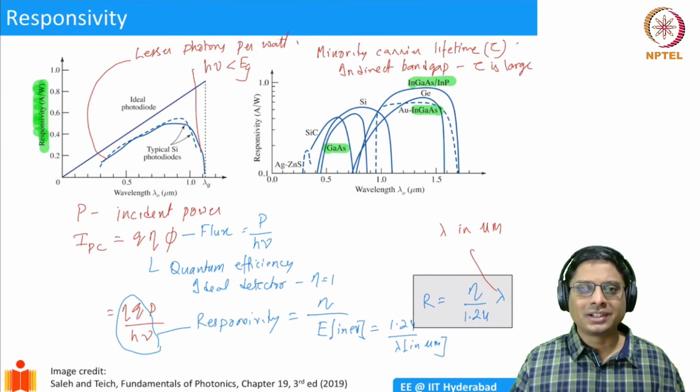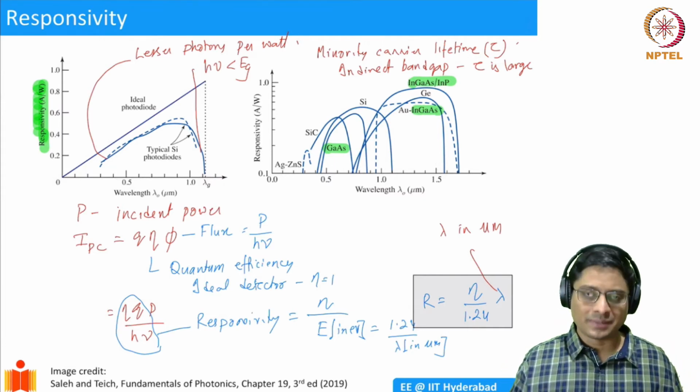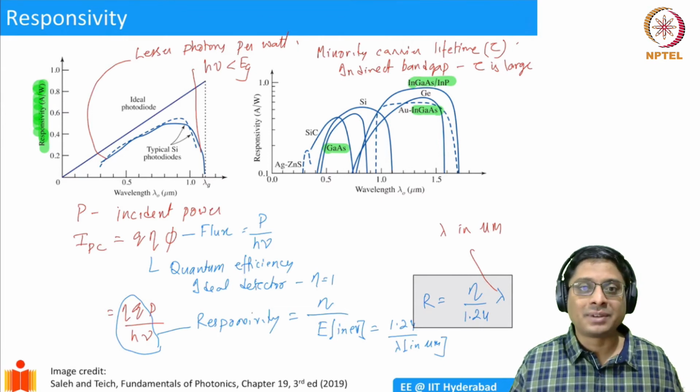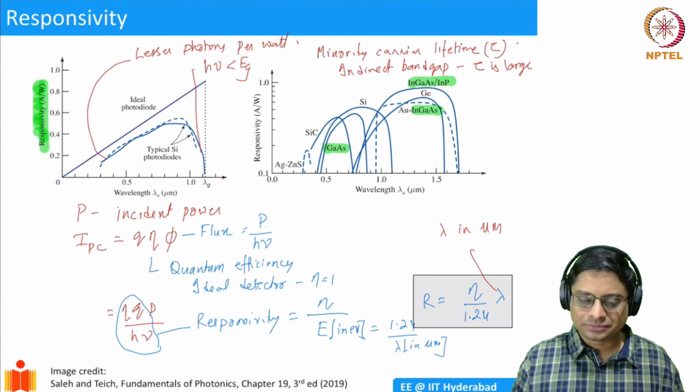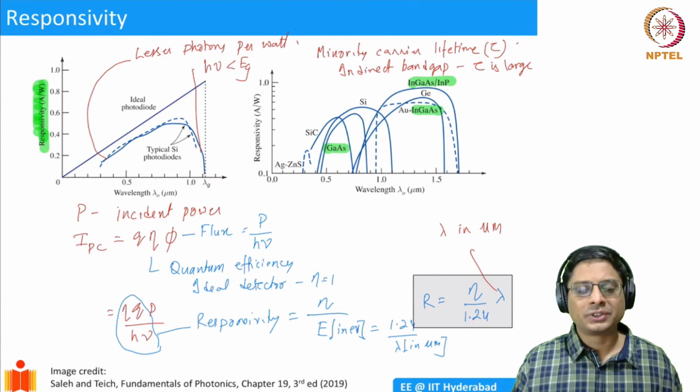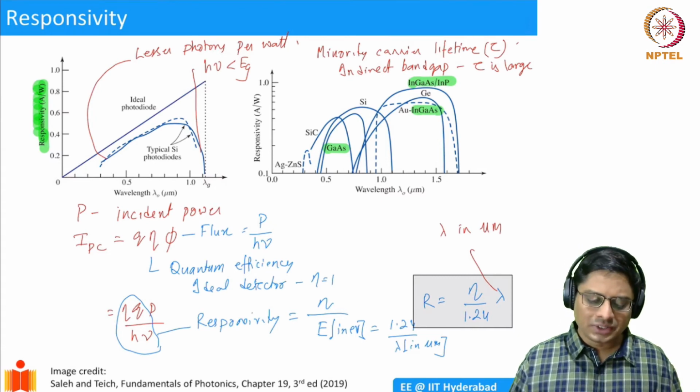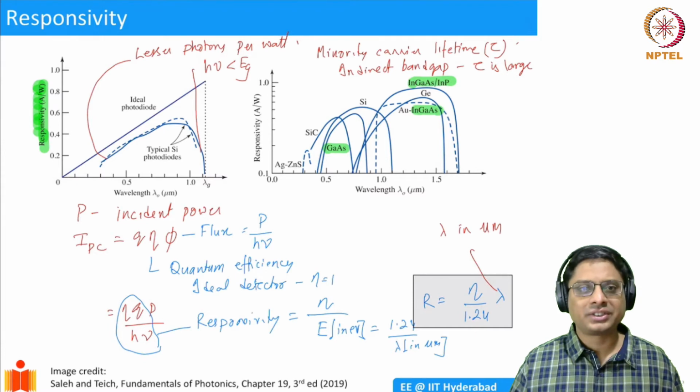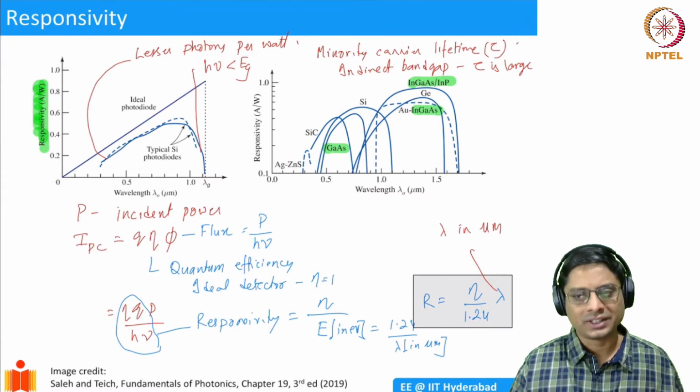For the same reason, in silicon you can also collect these electron hole pairs efficiently. That's why a silicon solar cell behaves reasonably well. If you build a gallium arsenide based solar cell, that's even better. Of course, we do that. It has much better efficiencies, but it's expensive. Silicon is cheap, so we try to use silicon solar cells. Similarly, you can make photodetectors out of silicon and germanium, and they still work.